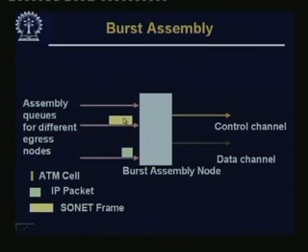This is the good thing about optics: if you are sending things purely in the optical plane, we do not really care what the payload contains. It may be an IP packet, a sonnet frame, some cell, or anything else, we really do not care. The intervening optics is transparent to all that.